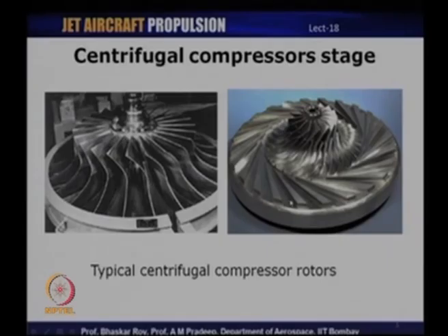what is shown here is a modern day centrifugal compressor design, much more complicated, as you can immediately see here. These are the inducer vanes, and then you can see that even the impeller vanes are curved. They are not straight, as you can see it here. Impeller vanes are straight in the older ones. Modern day designs have curved impeller vanes, and at the exit of the impeller we have the diffuser. This is known as a piped diffuser, and air here enters axially. It is guided through the inducer, and then it leaves the impeller and enters into the diffuser before exiting the